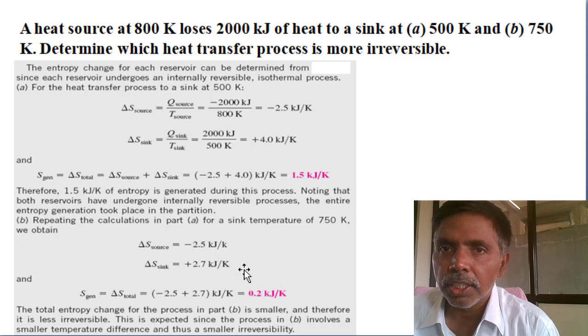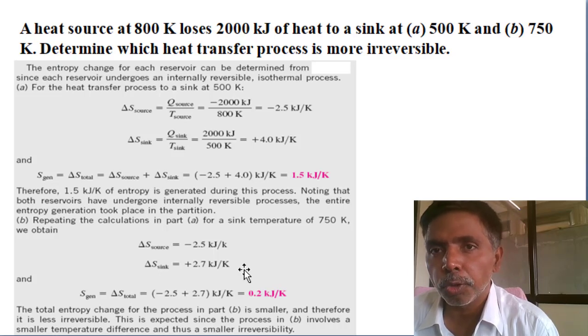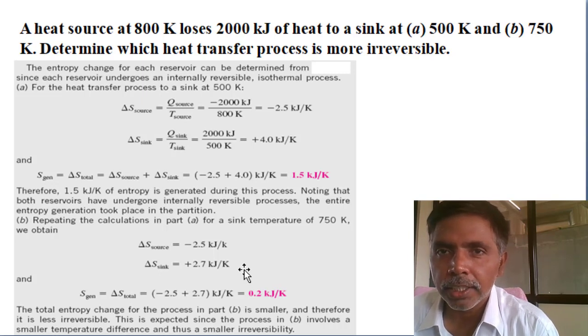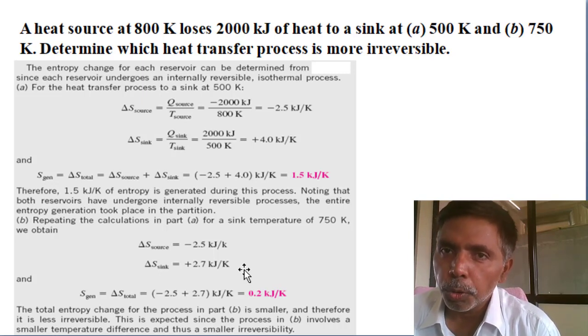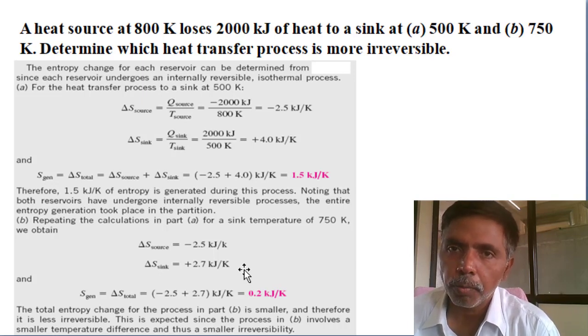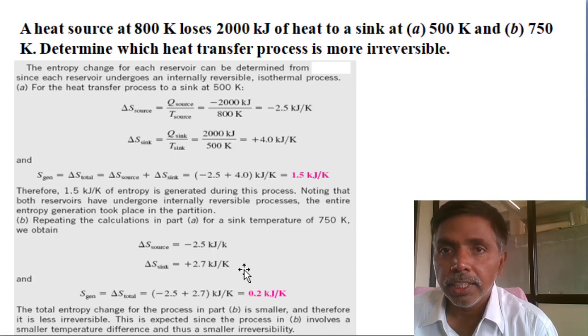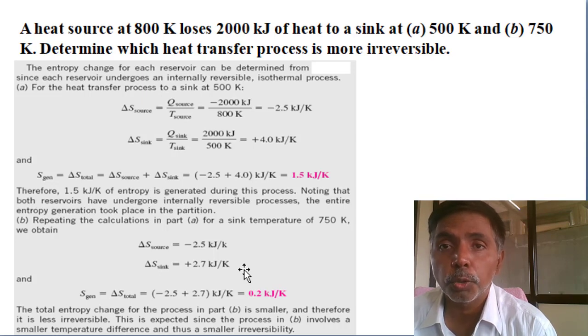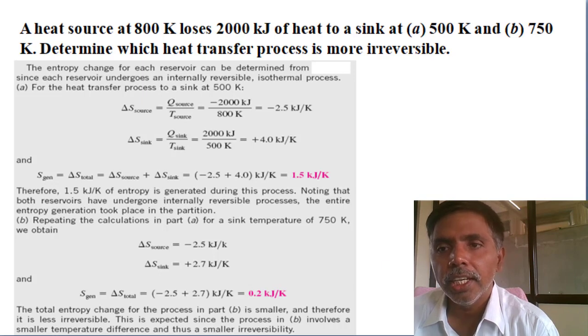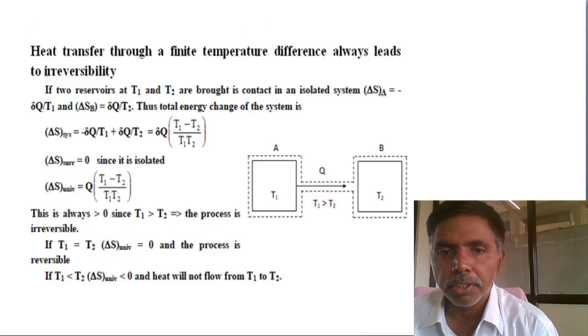That's why, especially for household utilities or low temperature thermal applications, the utilization of biomass, electrical energy or gas is almost removed. At present, they are using solar water heating systems, because the maximum solar source temperature is 90 or 80 degrees, and our utilization is also 50, 60 degrees. In the earlier condition, with gas, biomass or electrical energy, we used at least 300 to 400 as the source temperature. High temperature difference, high entropy generation, and the available energy is reduced. That is one application of entropy.